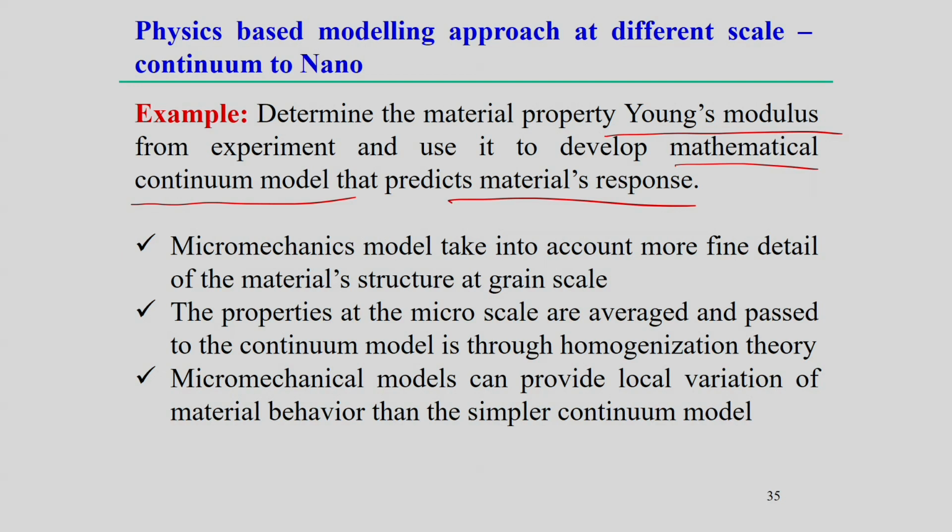We cannot use the Young's modulus for a bulk of material that we extract from the universal tensile testing machine when we try to predict the Young's modulus of a single crystal structure. In that case we need to refine the experimental procedure to find out the Young's modulus.